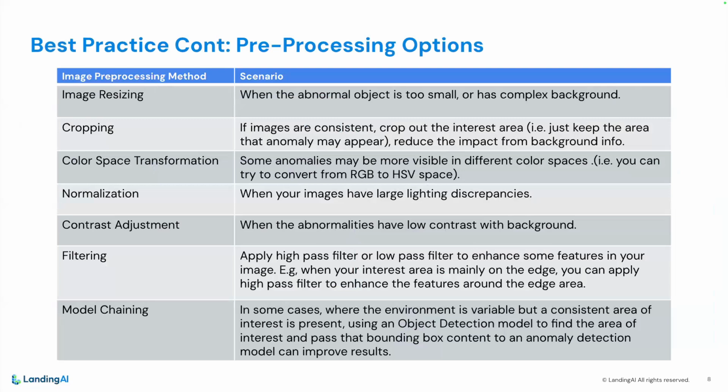And commonly, a lot of what you can do to optimize the anomaly detection model is pre-processing your data before it even gets into LandingLens. Currently, we resize images to 480 by 480. This is actually a little larger than most of the industry standard anomaly detection models available. So if you have use cases where you have very large images, you want to ensure that you're pre-processing so that you have at least 5 pixels of what you're looking to identify available in the training image.